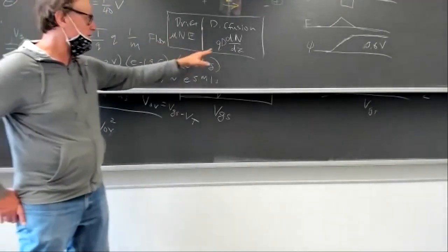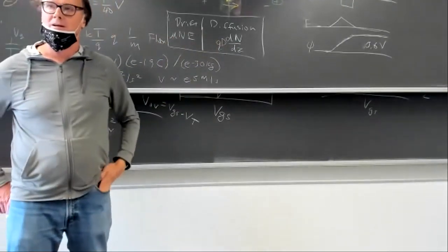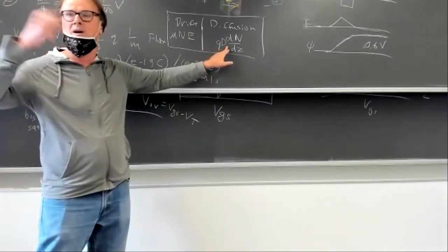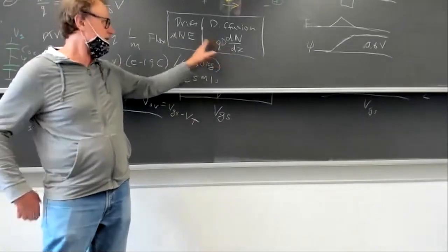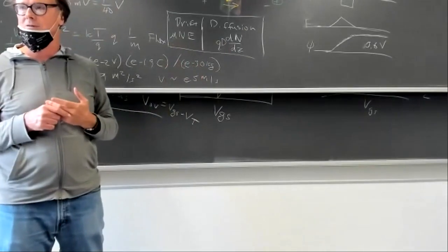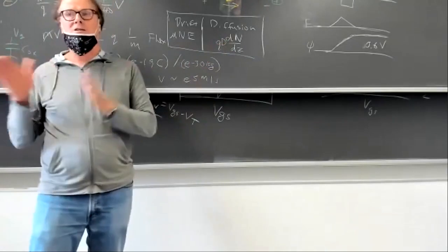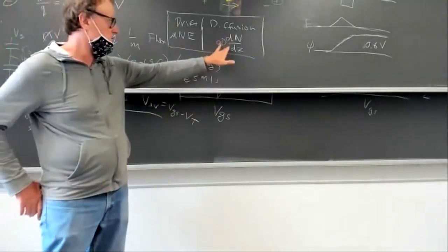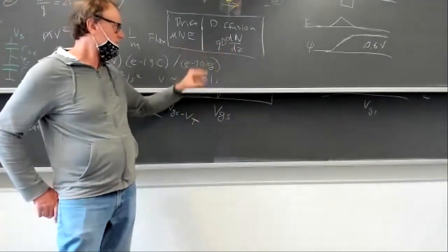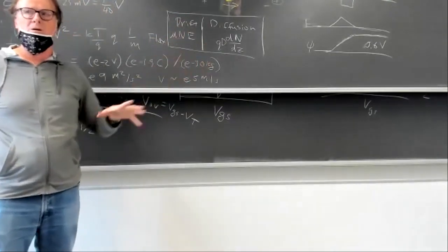Why should the diffusion constant depend on temperature but not mobility? It's very obvious why that is, right? Diffusion increases with temperature, because the hotter it is, the faster things move around. Of course, that doesn't affect how the carrier moves due to electric field, to first order. You never actually use this. Just be aware that diffusion is proportional to absolute temperature, and mobility is not, but both are a function of temperature.